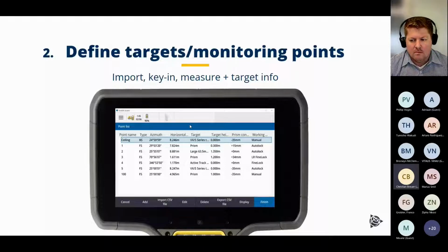One thing that you might want to look at here is that it is also important for monitoring that you are able to separate the prisms on site. I specifically mention this because on the monitoring side, especially when there is a road or a rail, or also just on a standard construction site, it can happen that the monitoring prisms are pretty close to each other. So you want to make sure that you use the appropriate lock mode.